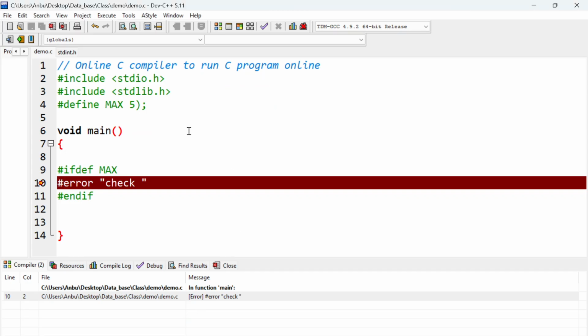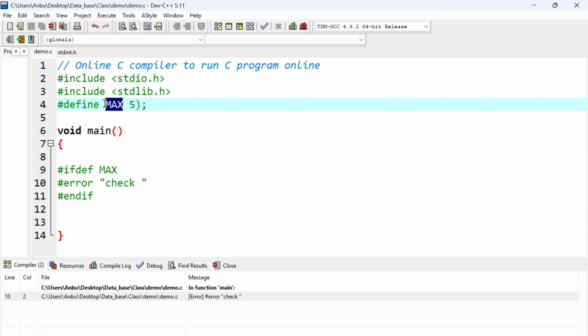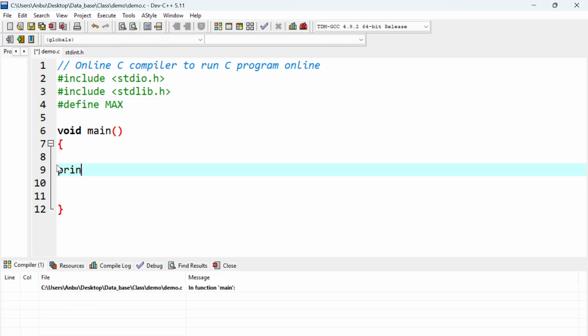So for example, let's try to understand this max, right? For max we are not getting any memory allocation, but if I am using the const keyword, max equal to 5, that will be stored in the code memory, which means the flash memory, definitely. But the preprocessor max 5 is not allocating any memory location in code memory or RAM for this max. But we have to understand, if it is a replacement, this data 5 is replaced here. For example, in print I'm doing, right?